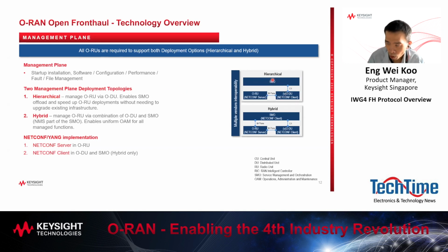The SMO or the network management system within the SMO would actually connect to the virtual ODU or the ODU over the O1 interface. For what's actually concerned of the open front haul, the ODU will run a netconf client, and the ORU would always have a netconf server. And basically, from ORU perspective, it's actually being managed by the ODU.